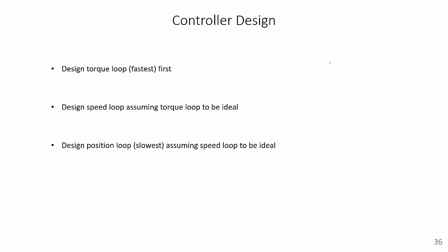It must be noted that when we have, say, 3-stage cascaded control with position being controlled, we cannot control the steady state speed and we cannot control the steady state current. There is only one control variable, which is the terminal voltage. Thus, you can only control one particular parameter using the terminal voltage. But what this cascaded control stage allows you to do is control the transient waveform of both the speed and the current, even though you can only control the steady state position and not the steady state speed and the current.